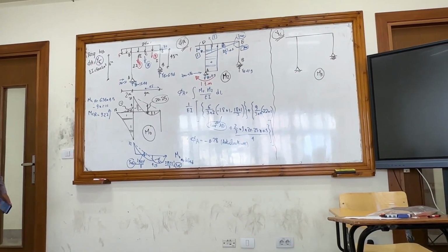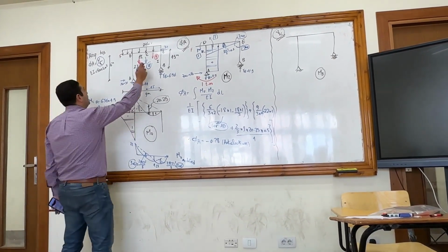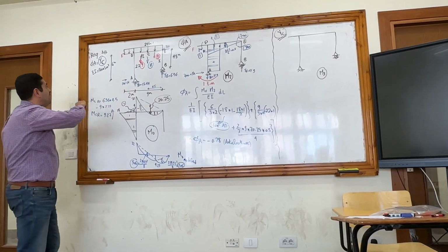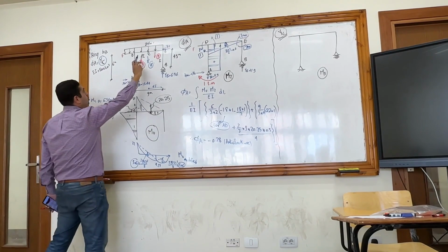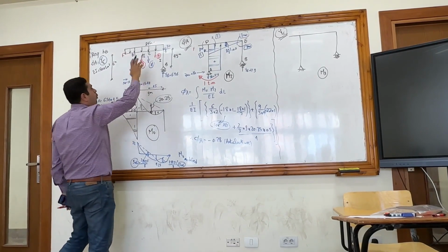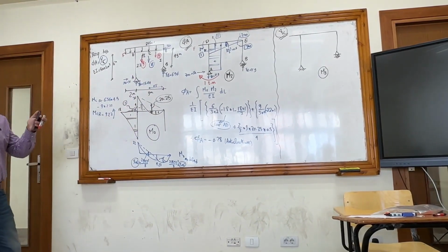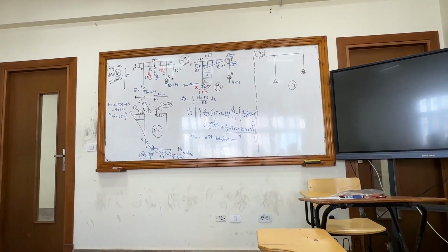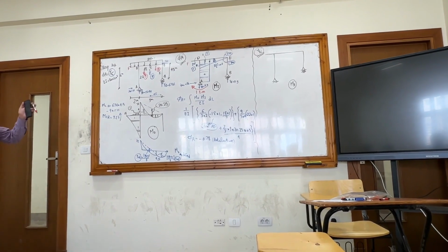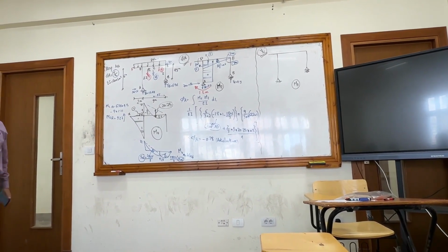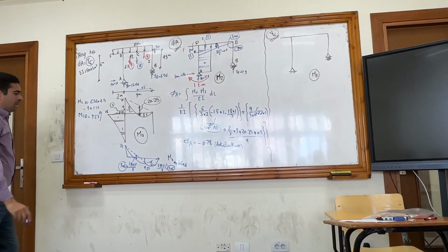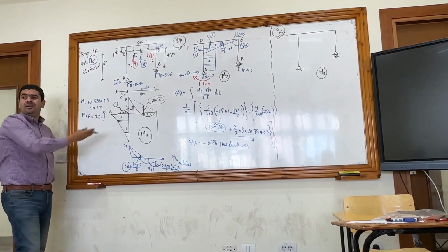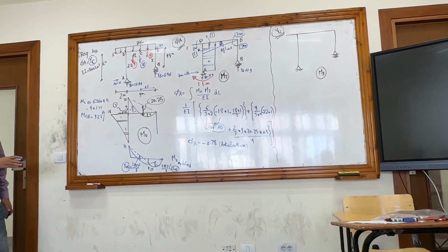Because I can't calculate the moment at C with the 18. Because now I have to deal with the one uniform distributed load in the member that was called DE. I have to deal with it as two distributed loads now, DC and CE. Okay? I think the answer for the question, why didn't I do that from the beginning, is clear now.